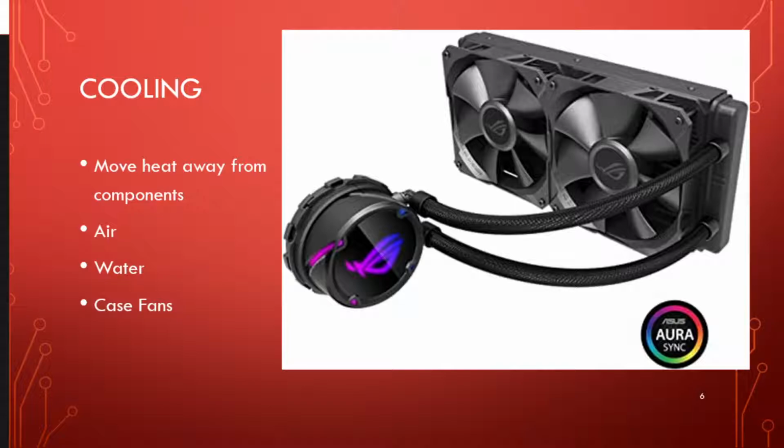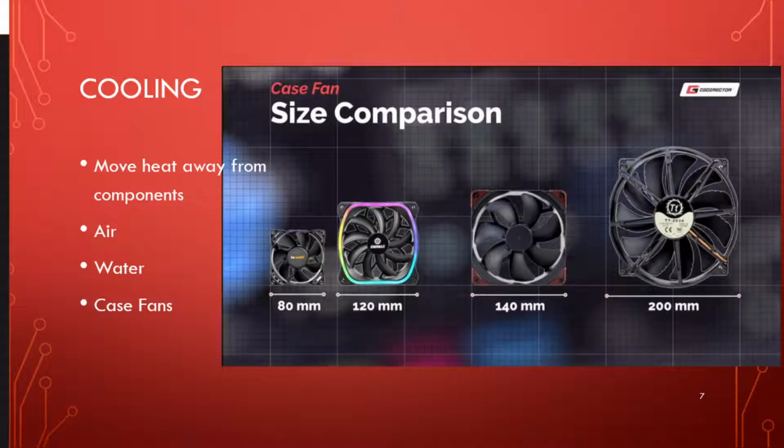And then last on here, I have case fans. And here is a lovely little picture for you. Traditionally, the larger the fan you can go, the quieter your computer is going to be. Larger fans can spin slower and move the same amount of air. So you do want to kind of go to the largest fan that you can.